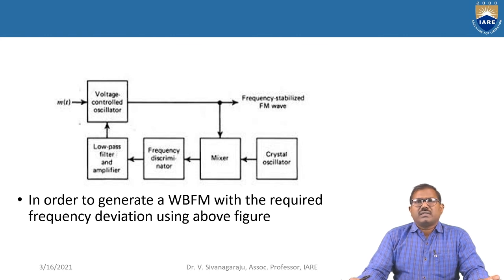And this is the figure we use to generate WBFM, that is wideband FM, with the required frequency deviation. We have a VCO, voltage controlled oscillator, low pass filter, frequency discriminator, mixer, and crystal oscillator. By using this figure, we can generate WBFM.